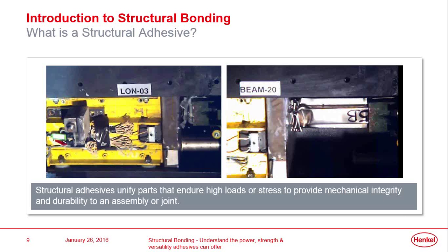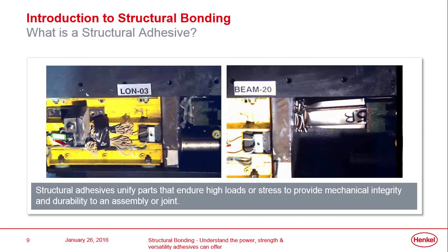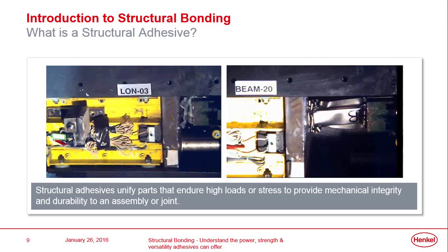Now, you can see why automotive manufacturers, for example, are beginning to utilize a combination of adhesive bonding and mechanical fastenings, because in a chassis structure, for example, this difference is perhaps the difference between broken ankles in a front-on collision and getting out of the car unscathed. And this is due entirely to this uniform stress distribution that adhesive bonding gives you over mechanical joining. And there's the final picture with the beams still intact to a degree.